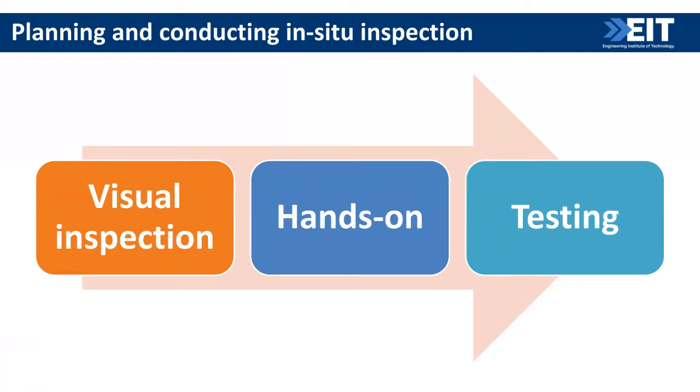Historically, we have in-place strength tests conducted when you have cores drilled from the structures, and you can combine this type of test with some non-destructive tests. Later on you can see this, but in-place tests normally permit a more economical evaluation of the concrete structure. But the critical aspect in this case is that, at the end of the day, we need to establish an accurate relationship between the in-place test results and the concrete strength.